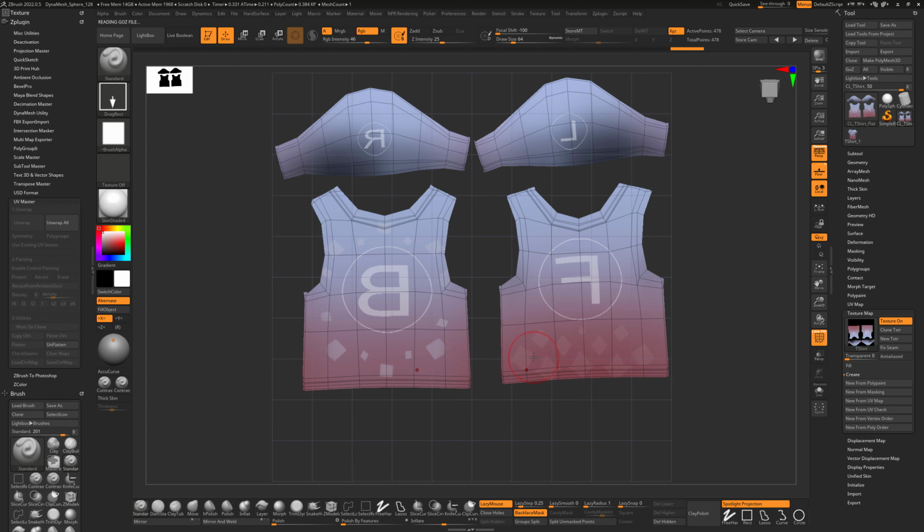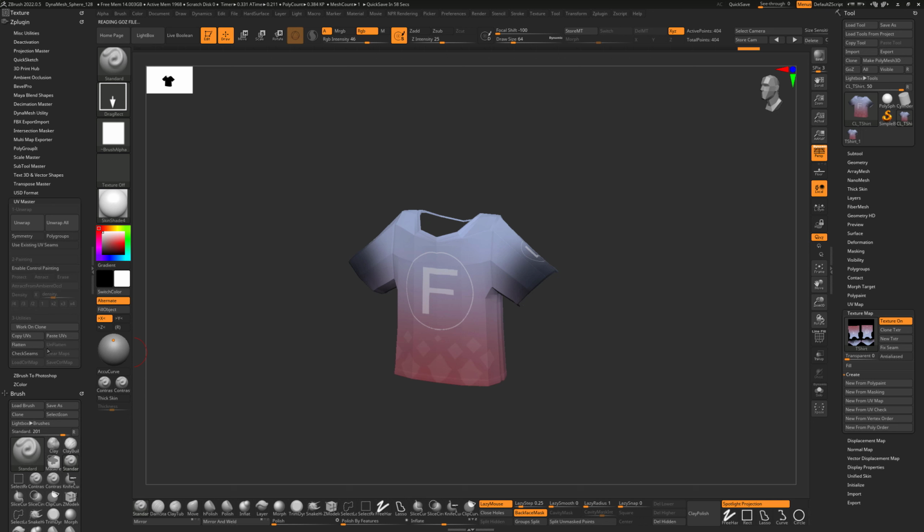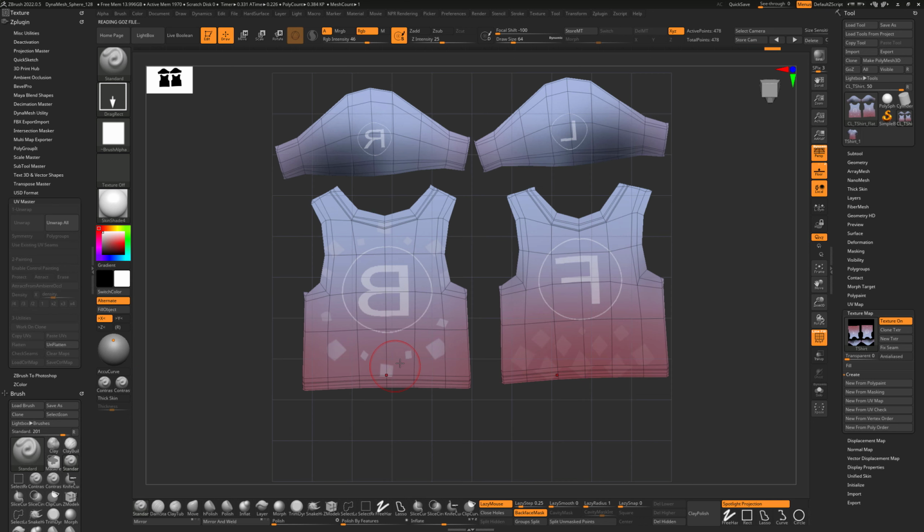Okay. So what I'm going to do is unflatten this, and I'm not sure if the UVs are exactly correct in what it's showing, but I'm going to unflatten that. What I was able to do was flatten this and export it out as an FBX model, and then I was able to do a morph target inside of ZBrush, or I'm sorry, in Maya, between this model and the old model that's split apart. And I'll show you the animation part in just a second when we hop over to Maya.